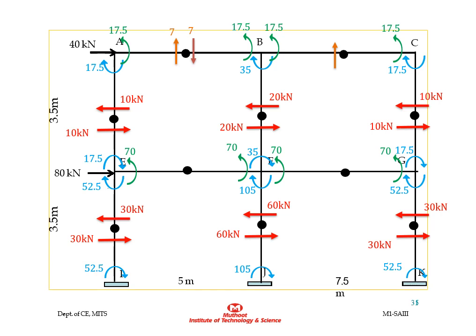Now we are going to calculate the beam shear for every beam. Since the moment at the midspan of the beams is 0, according to this assumption, the beam shear can be marked at the midspan of the beams.